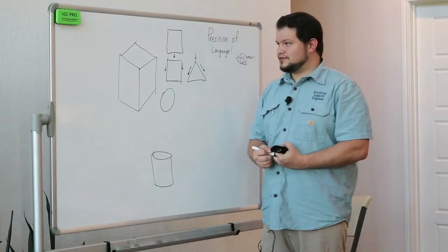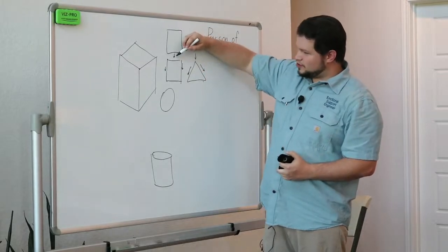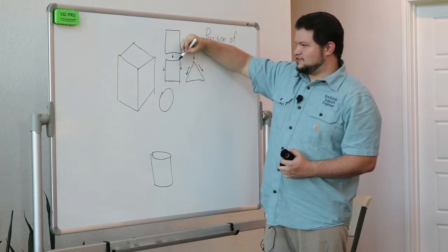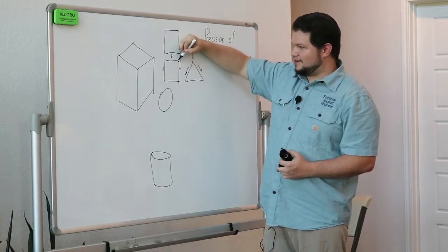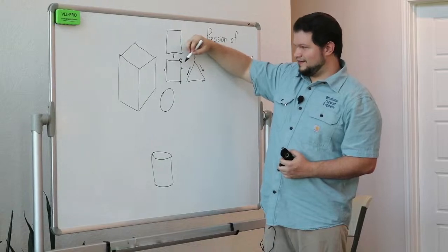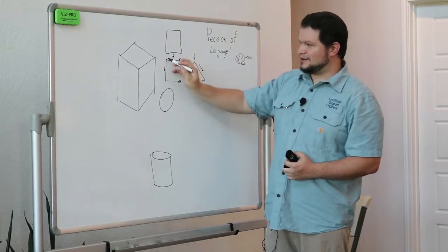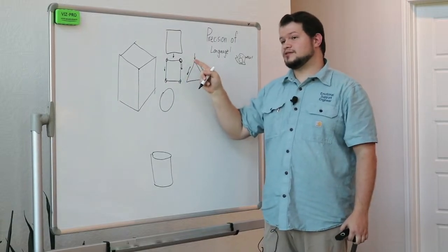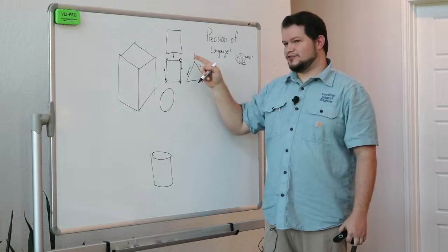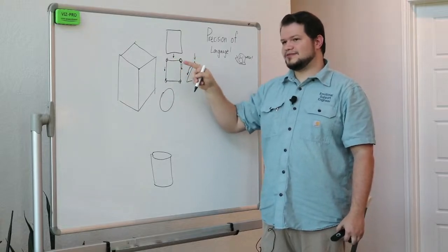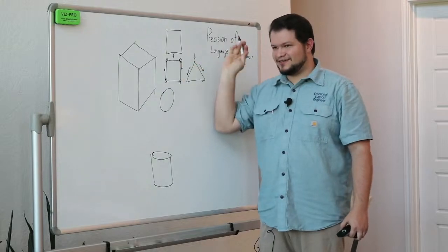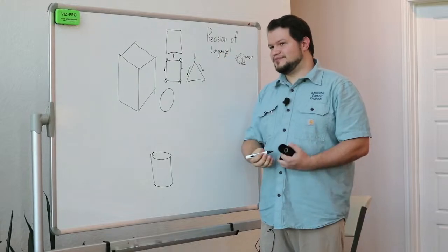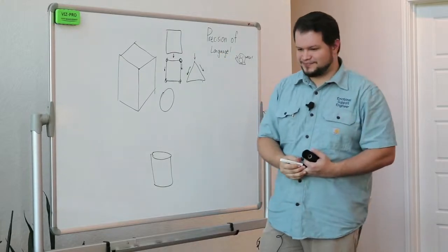No. The real reason is that when this force moves to go straight down, it has to travel along material. And so all of that force gets put right here in this corner. And then that same force gets put in this corner, and then same right here and here. And so these corners start acting like joints. And it's easy for me to take a 4-bar mechanism that has joints here and do this, and it falls over. But I can't do that with a triangle. As soon as I do this, it stays stable. So triangle is the strongest shape.